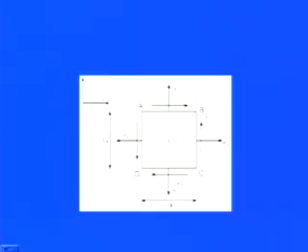The two normal stresses, sigma x and sigma y, and the two shear stresses, tau xy and tau yx, are sufficient to describe these stress components if we have unit width, with sigma x and sigma y in the corresponding x and y directions. Now, equilibrium is maintained only if whatever forces act around this structure, and whatever moments act about the pivoting point O, are zero.